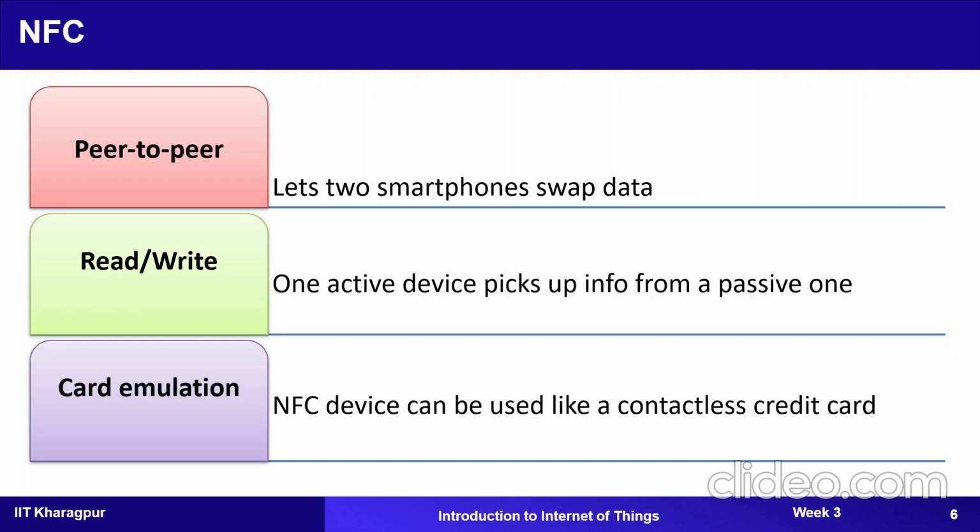Now the features of a piconet. Within a piconet, the clock and a unique 48-bit address of the master determine the timing of various devices and the frequency hopping sequence of individual devices. Each piconet supports 7 simultaneous connections to other devices. Each device can communicate with several piconets simultaneously, and such devices are called bridges. Piconets are established dynamically and automatically as Bluetooth-enabled devices enter and leave the piconet.